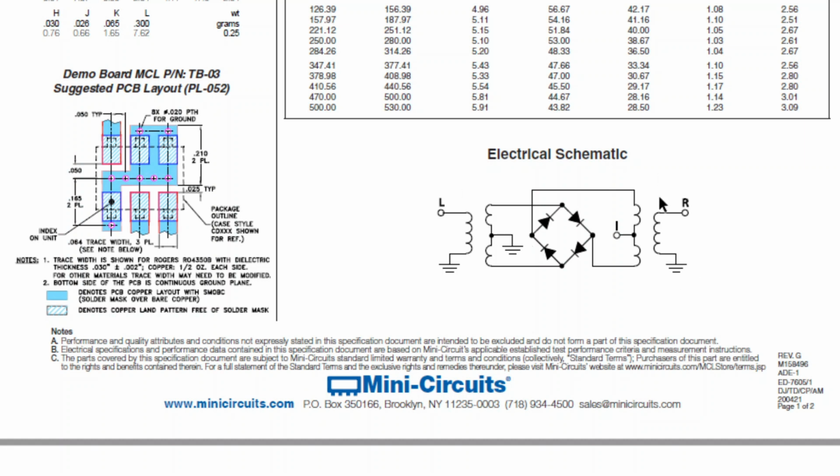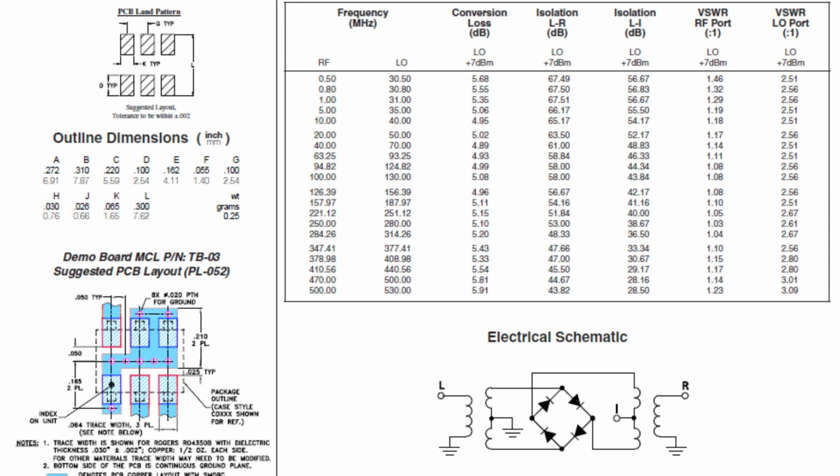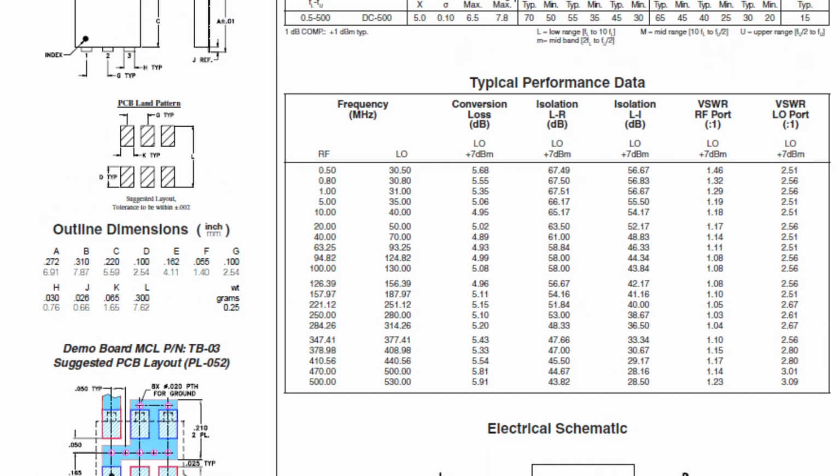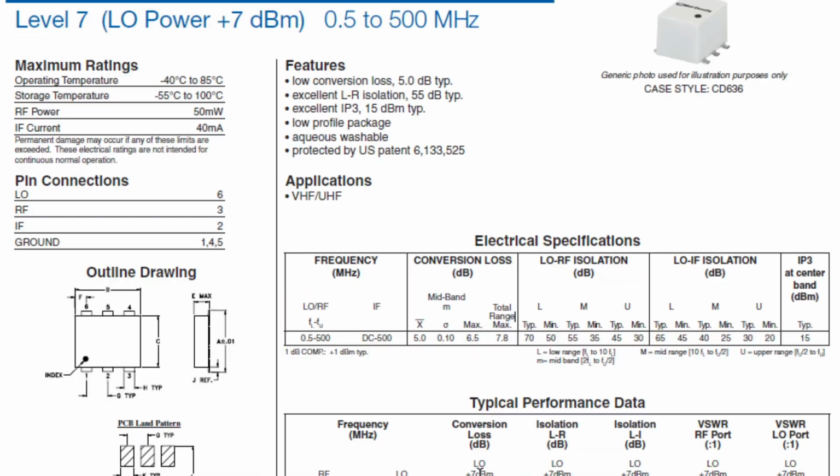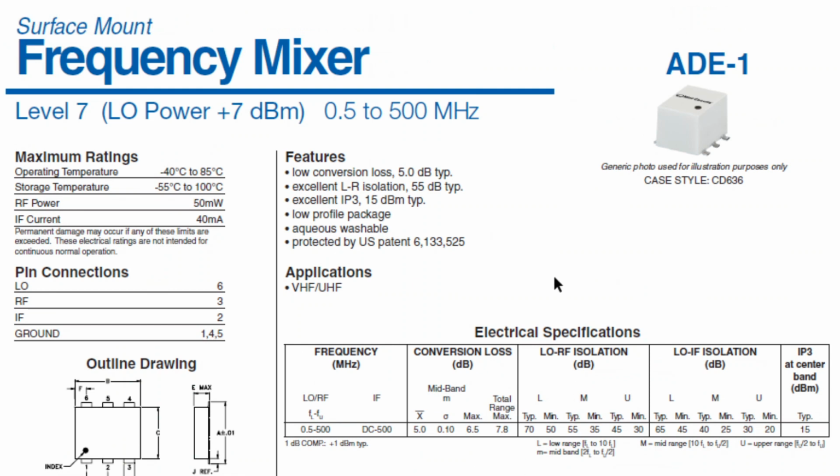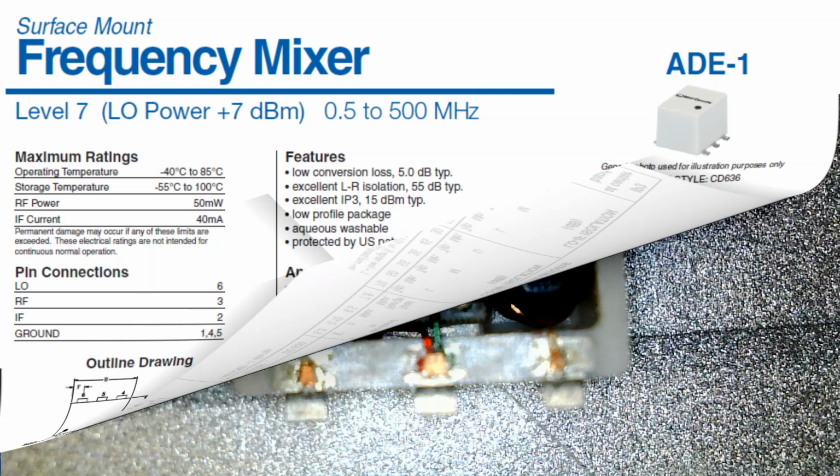So basically the circuit will have 2 of these with an IF clock that is 90 degrees out of phase to give me 2 signals, which the Teensy will then decode into audio. That's the plan. And so, Mini-Circuits supplied 4 of these for free as samples, and we'll just have to see how it goes.